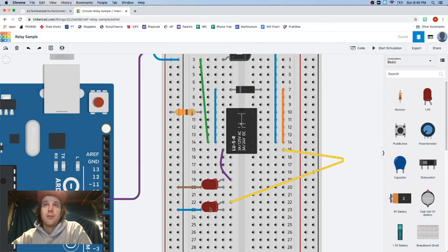Now, when port 9 is turned on, this is going to flip. When that flips, electricity is going to be flowing differently. It's always flowing through here; we're just controlling which direction it's going with the control circuit. So this is going to flip over, and then electricity is going to come down through the purple wire, out and up through the LED, and return to the negative section.